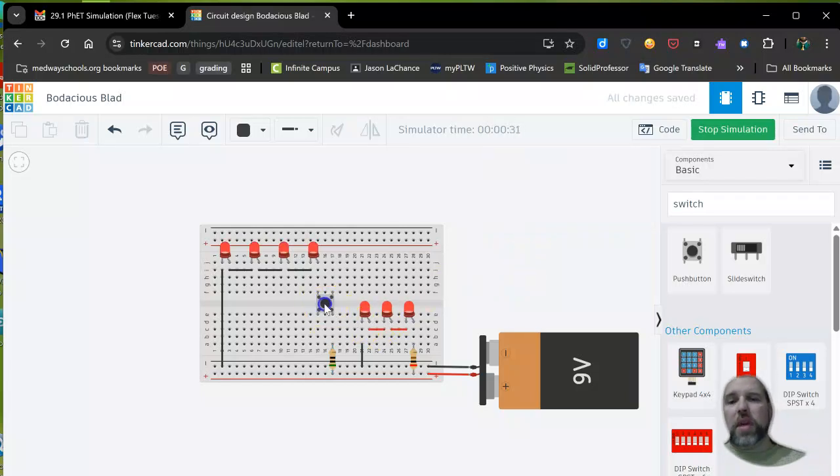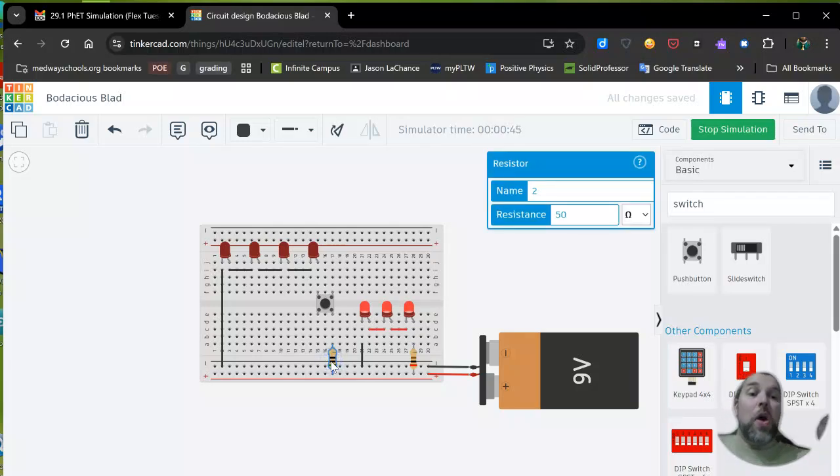Yeah, that's not bad. Because I have more bulbs here, that's taking up more of the voltage: 2, 4, 6, 8 volts. I only need 1 volt across this, so to get the right current, I don't really need as much resistance. But you can test this in here without burning out any bulbs. So there we go. We have this in parallel, and you can make more parallel branches of this as we go. Just know that each column here is connected, each of the rows are connected, so you can connect off the battery by jumping off any of these points. And let's try to build your circuit in here a little closer to real life and what that would actually look like. All right, you got this.